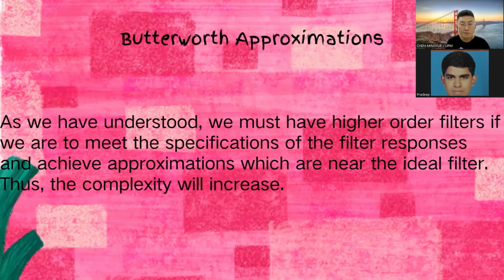As you can see here, I'll be discussing Butterworth approximations right now. As we have understood previously, we must have higher order filters if we are to meet the specifications of the filter responses and achieve approximations which are near the ideal filter. Thus, the complexity of the filter will increase.